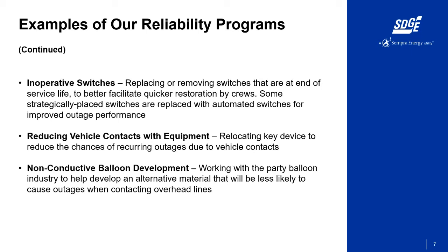I mentioned the SCADA program a little earlier. If we see that a particular switch which has reached the end of its service life has become a strategically placed switch over the years, we'll consider replacing that with a SCADA counterpart when we do the replacement work. Otherwise, these switches are considered inoperative while they're energized for safety reasons, and as such, their usefulness during that time is reduced in terms of service restoration. So we don't like to have switches out there that are in that mode for an extended time.